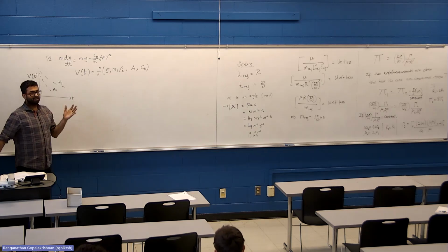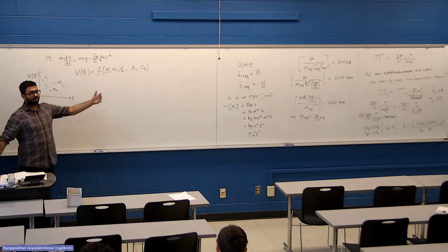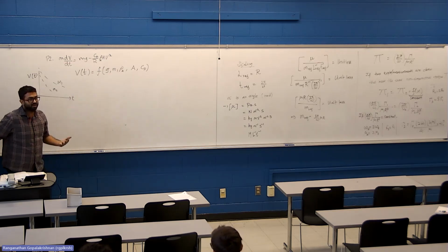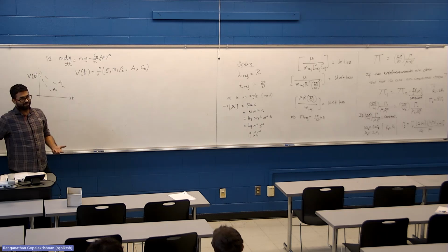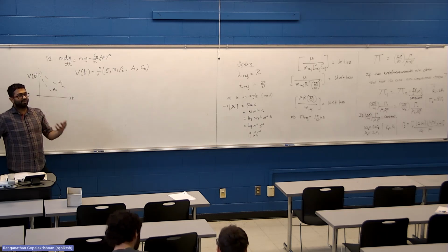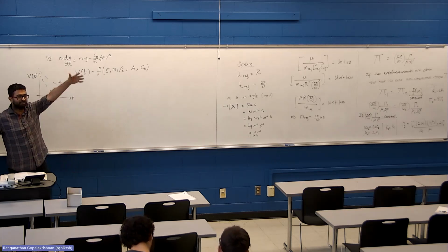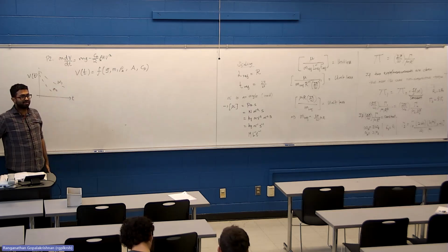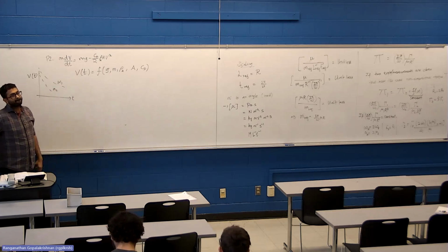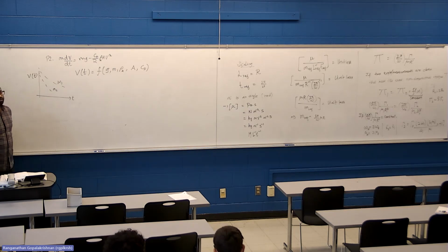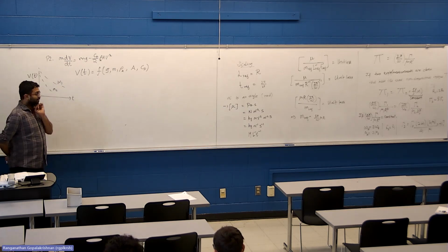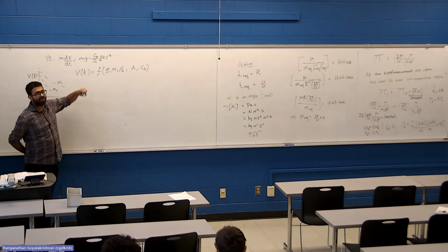Like if you think of another experiment where you take a single object, do the same experiment in two geographic regions where G is significantly different, then you can say G influences the problem. G is also a parameter you're varying in your experiment, although doing that in practical terms is quite tedious. Like you have to do an experiment in Memphis, travel all the way to Norway and do the experiment there. But if we're comparing two different experiments, they're just going to cancel, right? Because gravity is the same, the drag coefficient is the same. They will cancel in the sense they will have the same non-dimensional value.